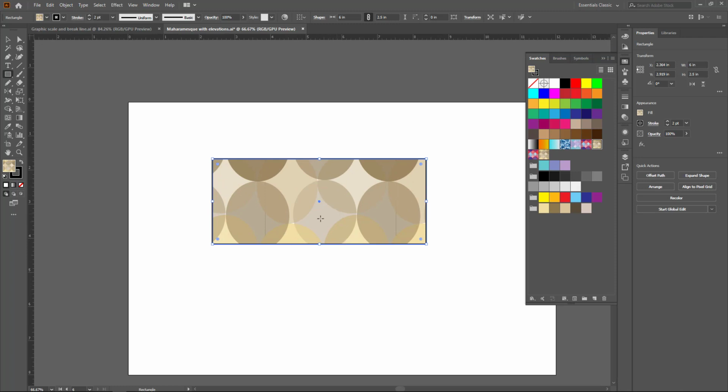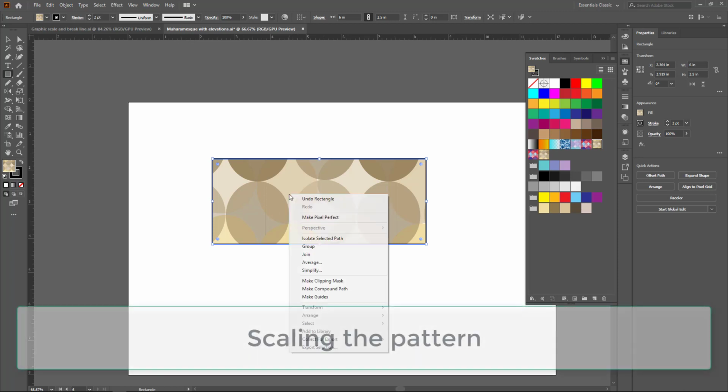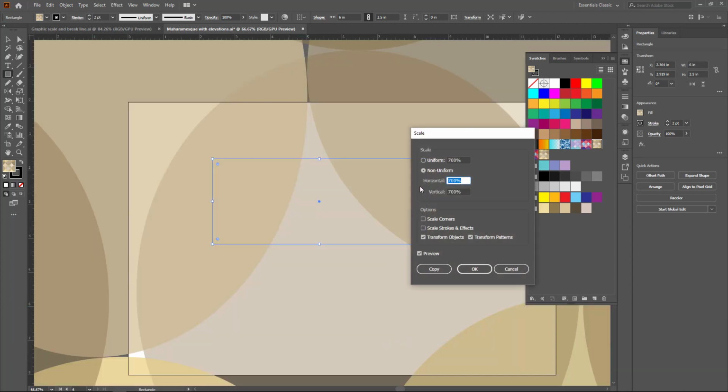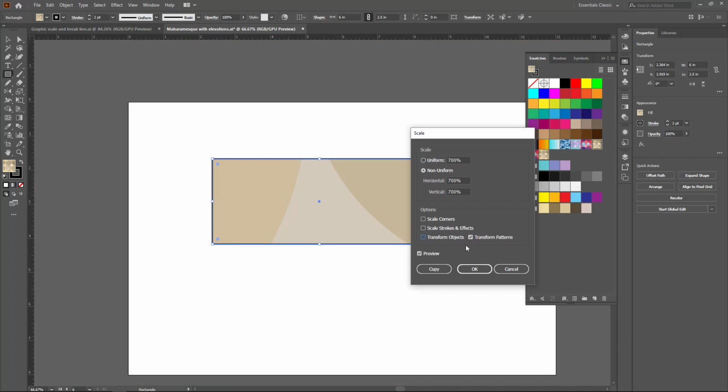And you might say, that's a little bigger pattern than I intended. I drew the pattern at full scale, and that's how it's drawing it here. But we also have to reduce the pattern to be at 1/4 inch scale. So I'll just right click on the pattern, choose Transform, Scale. Now, my screen is going bananas because I'm scaling the whole object. I want to transform just the patterns. See how I uncheck all of these other options.